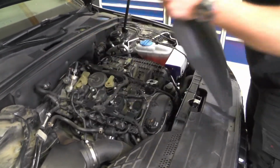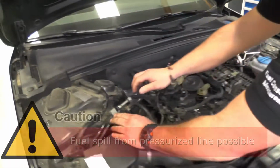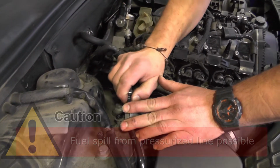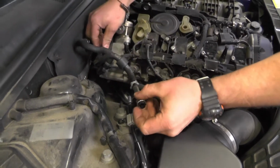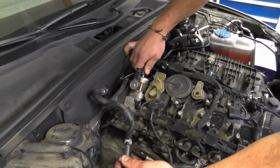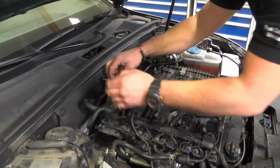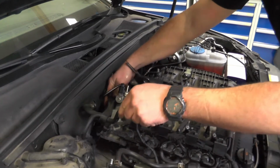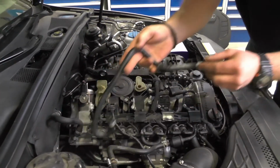We will start with opening the quick connector of the supply line between the tank and the engine, or in this case between the tank and the high pressure pump. Be careful, this line could be under pressure, so a small amount of fuel could spill out as you open the connector. In this particular installation we remove this vehicle fuel line segment between the quick connector and the high pressure pump.